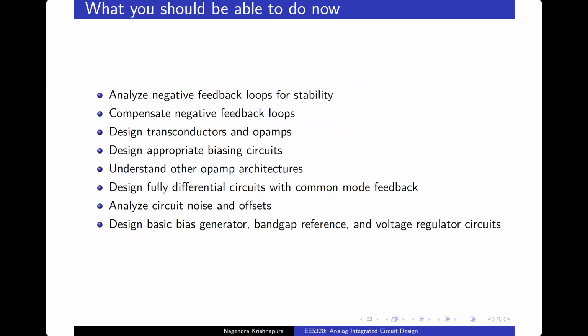So let's say you design it without including this body effect. You think that you can have 500 millivolts of signal, and in simulation you find it is less. And with further simulations you can find that this is because of VT change due to body effect. So one goal may be to predict this, but actually the more important goal for a designer is how to get it back to 500 millivolts. So that you can do now based on everything else that you know.